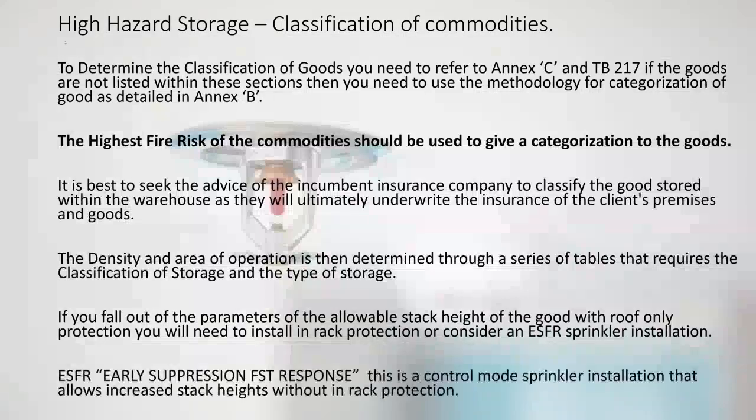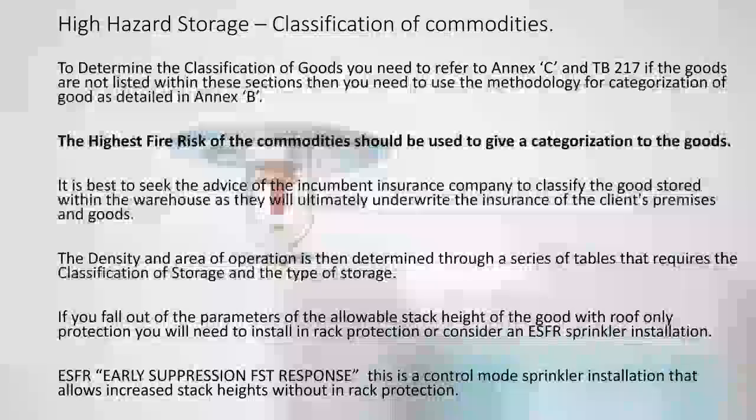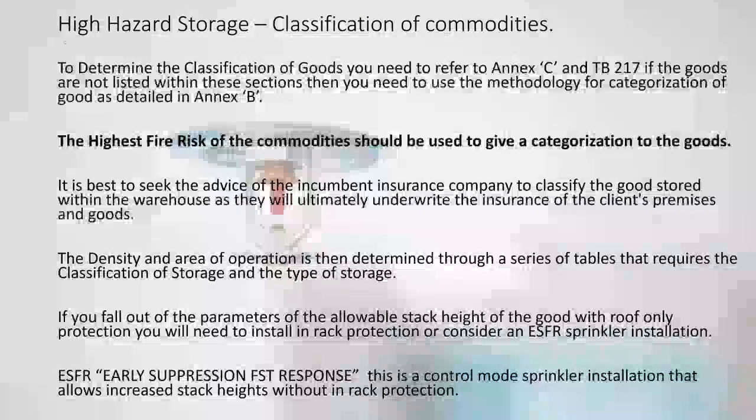Now, ESFR is early suppression fast response. That's a control mode of sprinkler installation. Basically it's 12 heads in operation at the roof. And if you can imagine, you've got 12 hose reels at the roof shooting water straight down to the floor, because they operate at 3.5 bar. You've basically got hose reels shooting a lot of water straight down to the floor to extinguish the fire, and they act really quickly.